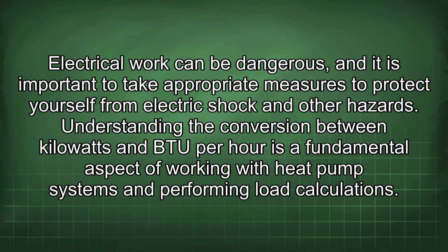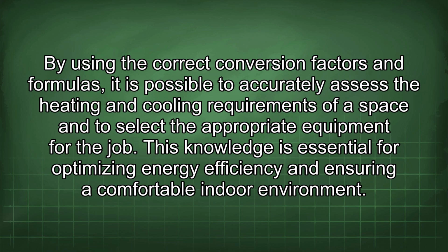Understanding the conversion between kilowatts and BTU per hour is a fundamental aspect of working with heat pump systems and performing load calculations. By using the correct conversion factors and formulas, it is possible to accurately assess the heating and cooling requirements of a space and to select the appropriate equipment for the job. This knowledge is essential for optimizing energy efficiency and ensuring a comfortable indoor environment.